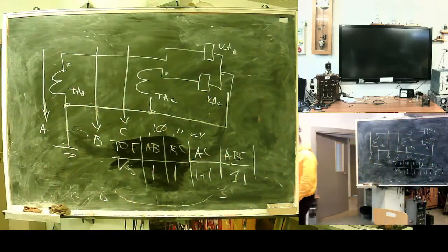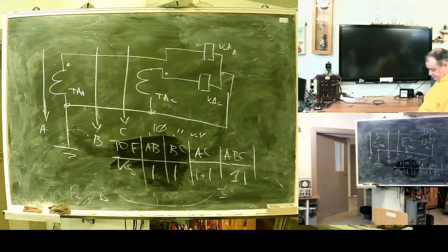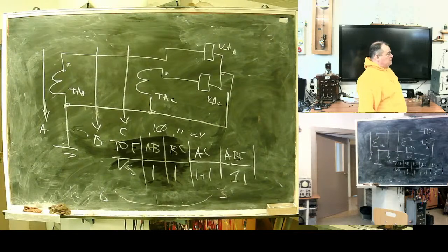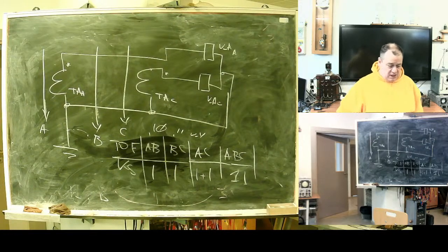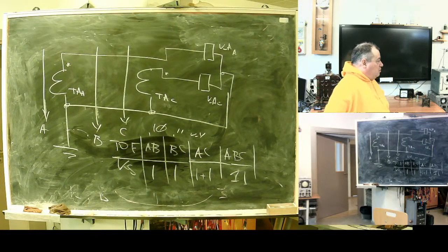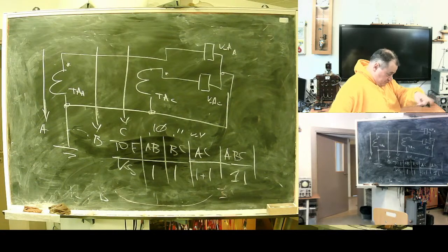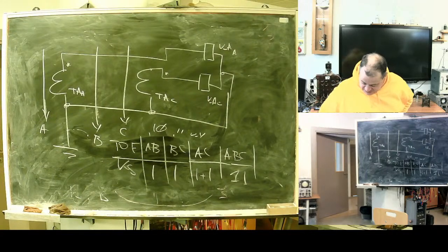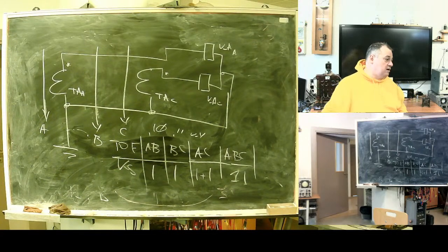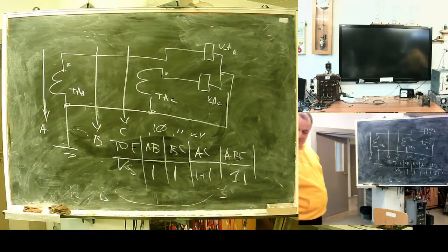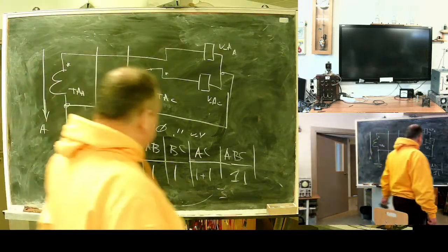It appears this thing is usable. But something is wrong. Really, in case of isolated neutral network, this works, no? In any possible fault, for ground fault, anyway we need zero sequence relay with zero sequence transformer.